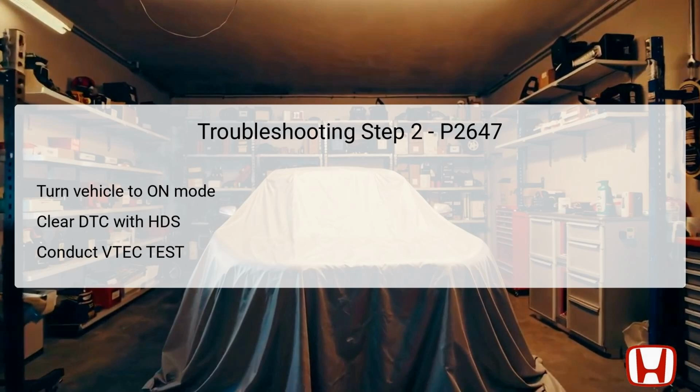Following the DTC clearance, conduct a VTEC test using the HDS. This test assesses the operational status of the variable valve timing system, ensuring that the rocker arm oil pressure switch is functioning correctly. If the test results are satisfactory, it indicates that the issue might be intermittent, suggesting that it could be necessary to check for loose connections or poor terminal contact. If the test results are not satisfactory, further investigation into the fault is warranted.